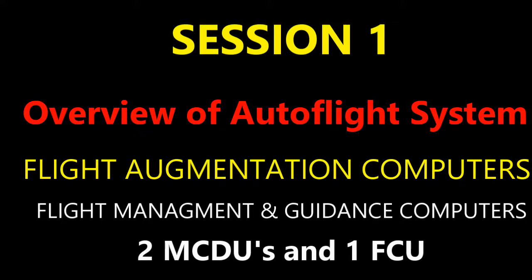And incidentally, what controls the flight mode annunciator? That's going to be your FMGCs. Actually, in particular, you have two FMGCs, but there's one master one, because remember, these are redundant systems, which is why we have two, but there is going to be one as the main one. That's going to be supplying both the FMAs, both the flight mode annunciators. And your FMGCs are going to be displaying that autothrottle information. So that's the connection, if you will, between the flight mode annunciator and the FMGCs. Okay.